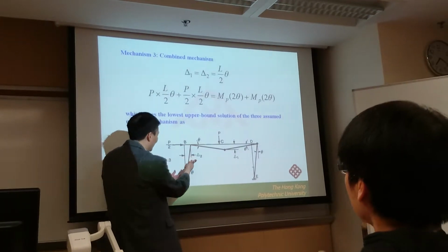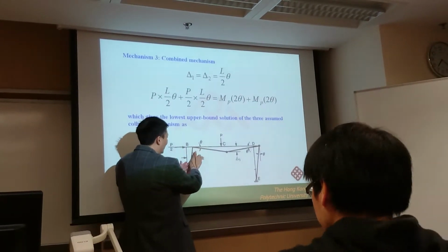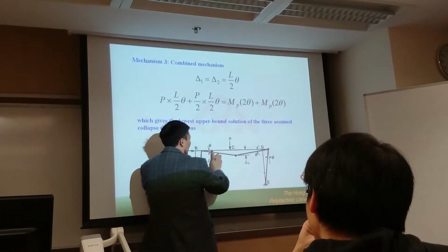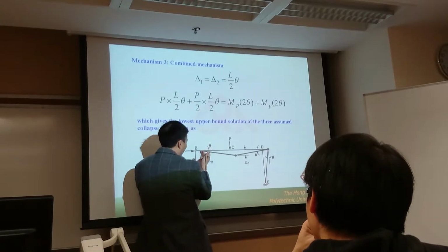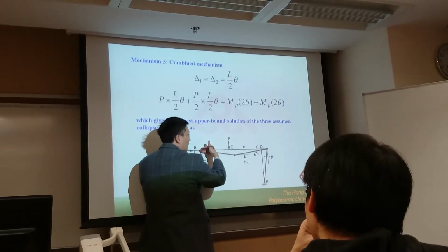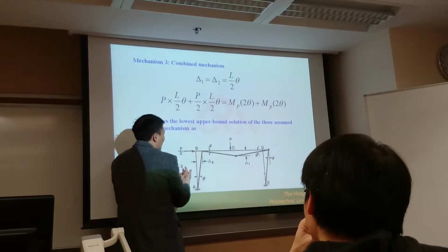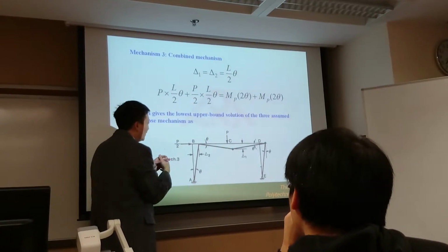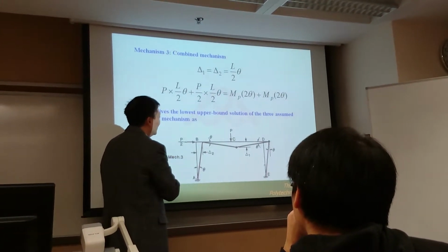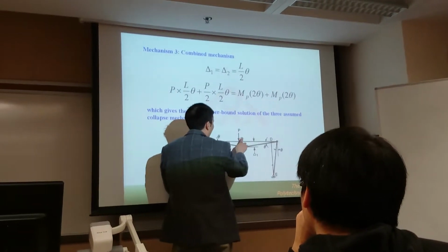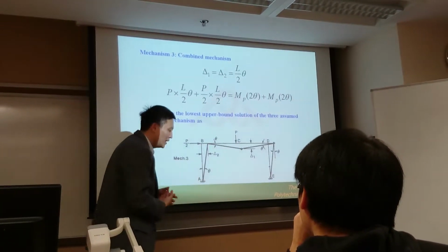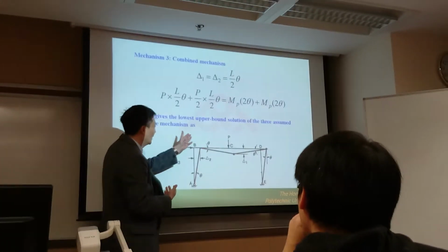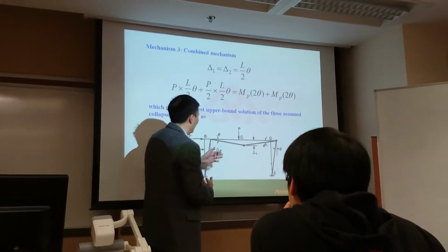Of course, when you introduce a horizontal displacement, you have to move the beam in the horizontal direction, and then at this point there is a change of the rotation angle, and then you can obtain the MB value. So you can assume the virtual horizontal displacement, but I do not recommend getting the solution this way, because a virtual displacement just in the vertical direction provides you the simplest virtual work equation to get the solution for MB.